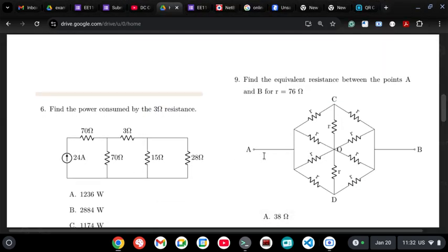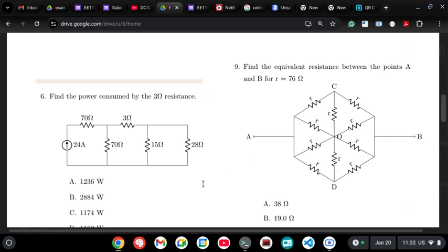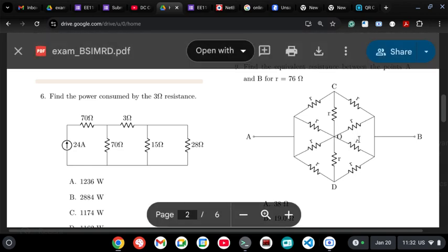So again, we are talking about question number 9 here. There is a circuit given, and we are supposed to find the resistance between A and B. How I would do it is I see that here these two R's become R by 2, and on the right also this becomes R by 2, because two resistances are in parallel, and this side it is anyway complete.